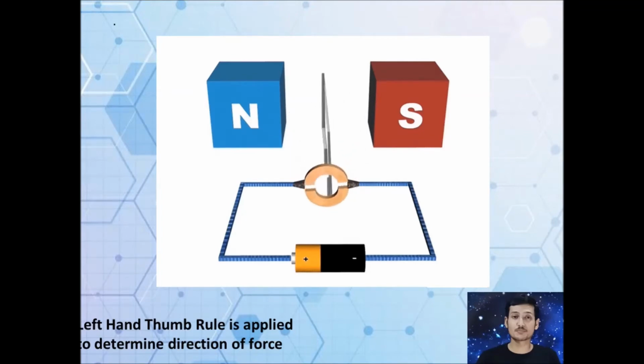The force is getting applied downwards, and on that side the force is getting applied upwards, so this is rotating. Then again, after half rotation, your coils are getting interchanged. Again, the force will be applied downward on one side, and on the other side the force is applied upward, so they keep on rotating.